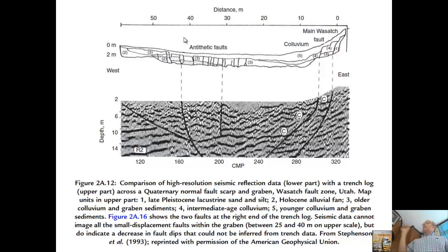But I don't want to be overly critical initially. When you're more familiar, you may say, no, that's a very clear break. But sometimes it's difficult to only use the geophysics by itself. So what would be very helpful is to have a core here or a CPT profile so we can look for what the interfaces may be and tie it back into the interpretation.